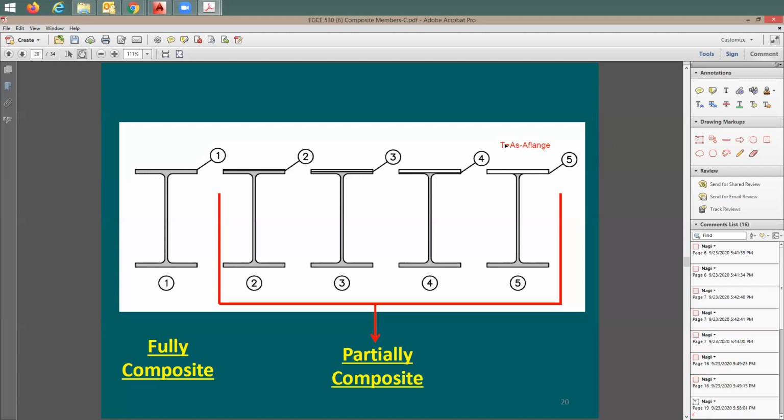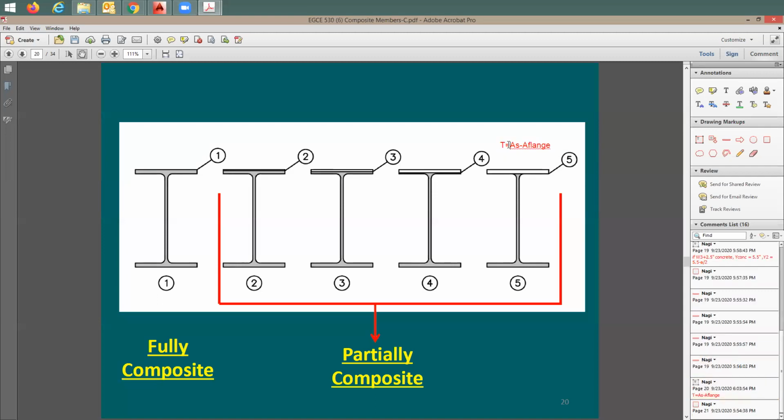And then you multiply, this tension is going to be equal to this As, just to be correct, times Fy, if this makes sense to you. So the effective area here is going to be equal to the entire cross-section area of the steel beam subtracting the flange area, times F sub y.